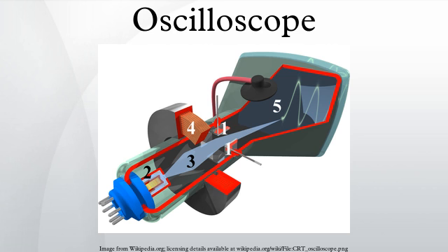Other instruments convert the results of their measurements to a repetitive electrical signal, and incorporate an oscilloscope as a display element. Such complex measurement systems include spectrum analyzers, transistor analyzers, and time-domain reflectometers. Unlike an oscilloscope, these instruments automatically generate stimulus or sweep a measurement parameter.